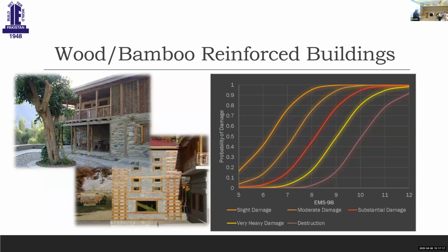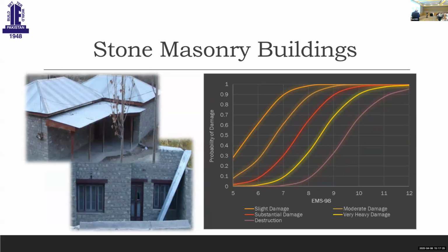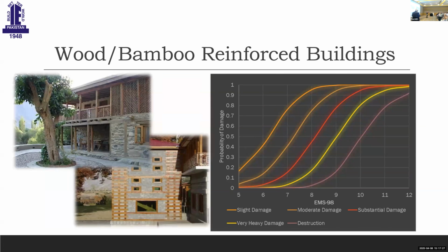Based on this, the probability distribution is what is called the fragility functions. I'll just explain one of them. Looking at this, the intensity scale goes from 0 to 12, but obviously anything less than 5 is not worth mentioning. And these are the 5 different damage grades: D1, D2, D3, D4, and D5.